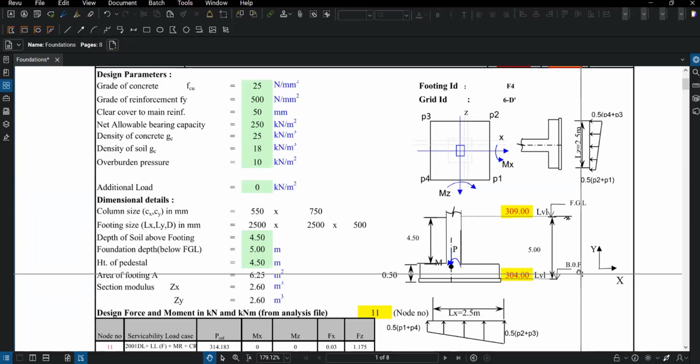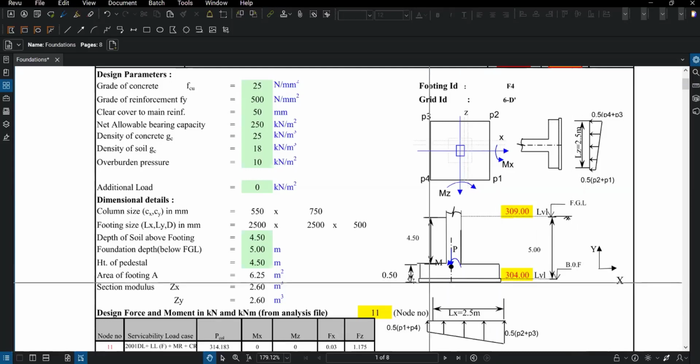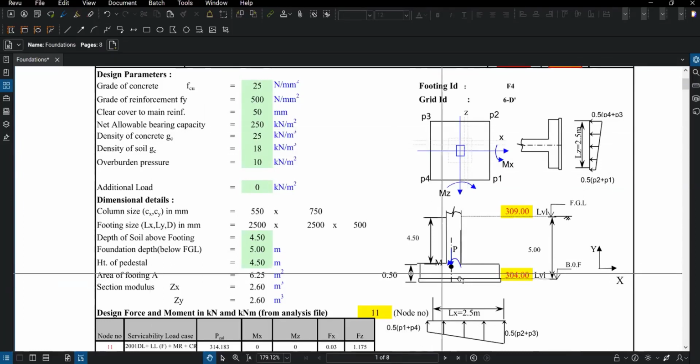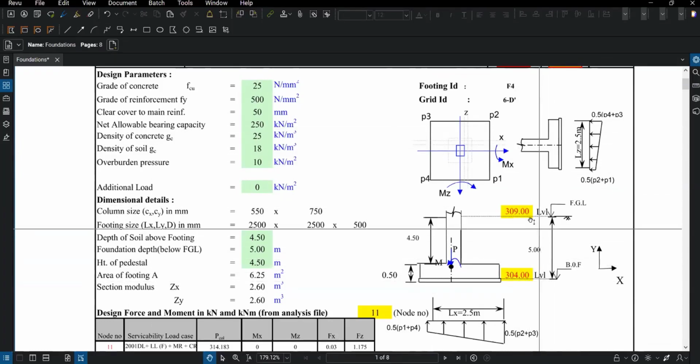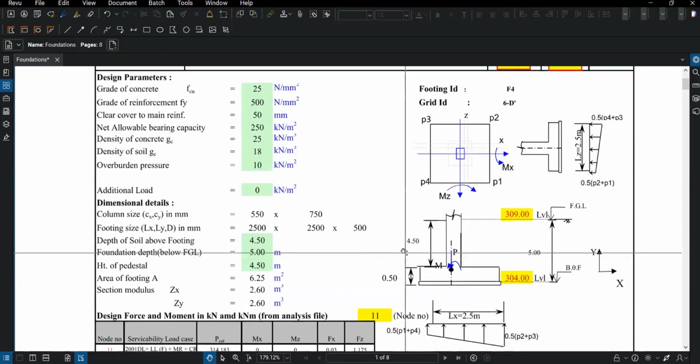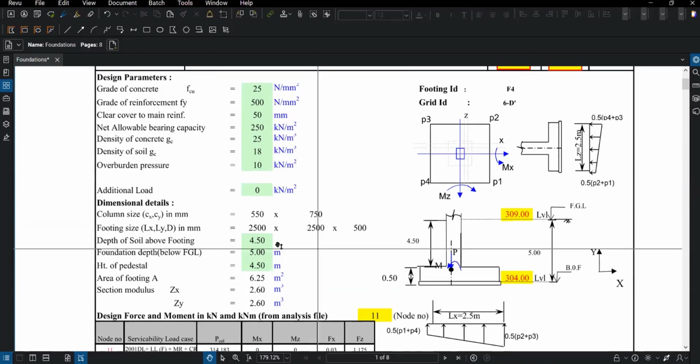The entirety of the mass of the soil which was already there, the bearing strata was also bearing that mass as well. So the gross bearing capacity of that particular strata is the net allowable bearing capacity plus the addition of the mass of the 5 meters of soil. All right, that is the basic difference between net and gross, basically.